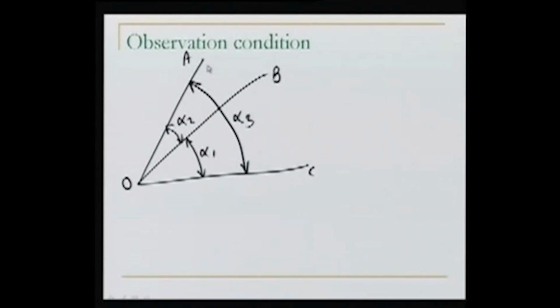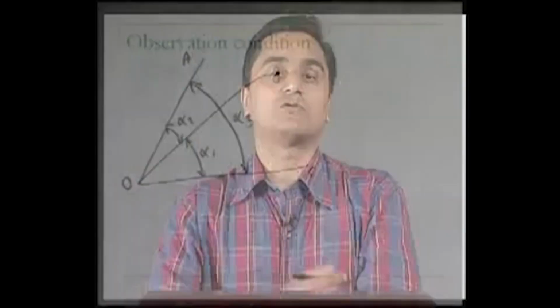Now just think of the case of theodolite. What do we do in the theodolite? We'll take the theodolite, we'll set the theodolite at point O. It should be exactly above point O. The vertical axis of the theodolite should pass exactly over the point O. Will it be so? No. There are problems in centering. We cannot center truly. There is some error.